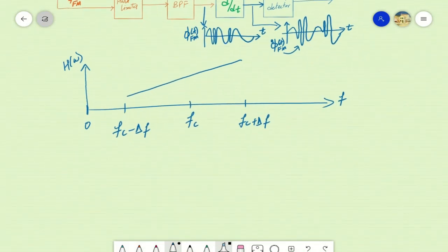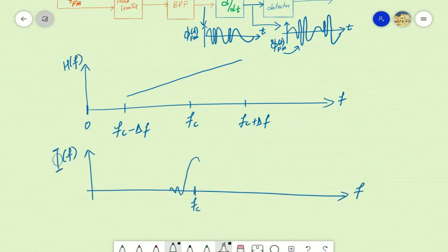If we plot the input frequency modulated signal in frequency domain here, if you recall, a sinc positioned at frequency fc was generated, while for different amplitudes of the information signal, this sinc experiences a shift along the frequency axis. When a maximum amplitude of the information signal is observed, that is a peak amplitude of the information signal, a maximum shift in the central frequency of this sinc is observed, and a maximum deviation, that is delta f, is experienced in the frequency of the modulated signal.